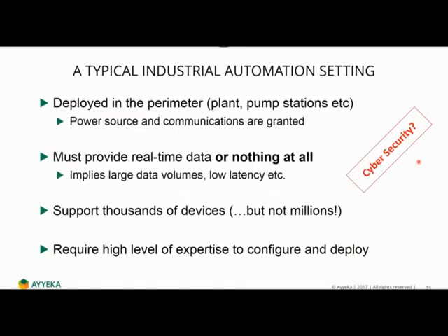What about cybersecurity? Well, that was not part of the plan. When you look at classic industrial automation protocols, it's just not there. Modbus is plain text, open, no encryption, no authentication, and so on. And other protocols suffer from this to a different degree. It was just not considered when they designed it.